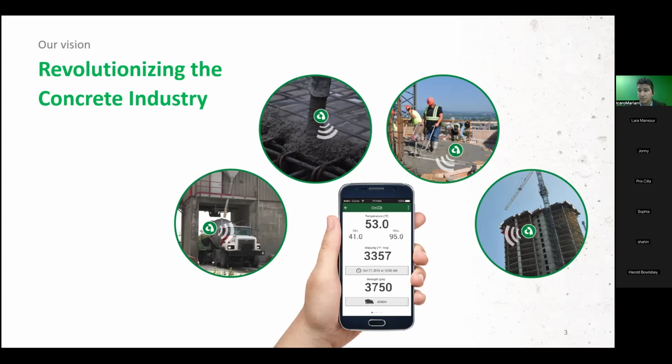Yes, yes, absolutely. Because if you think about a large pour, let's say we're talking about 1,000 cubic yards, you always needed to have a field technician taking notes. Okay, now concrete is covering that sensor, and now it's covering that sensor, taking manual notes. With the system implemented, the sensor can actually detect that pouring time alone. So the strength gain begins at that given point in time. It gives more precision to the data you're getting out of the sensors. Because in the end, if you don't know the start time, you're actually skewing the data in the future.